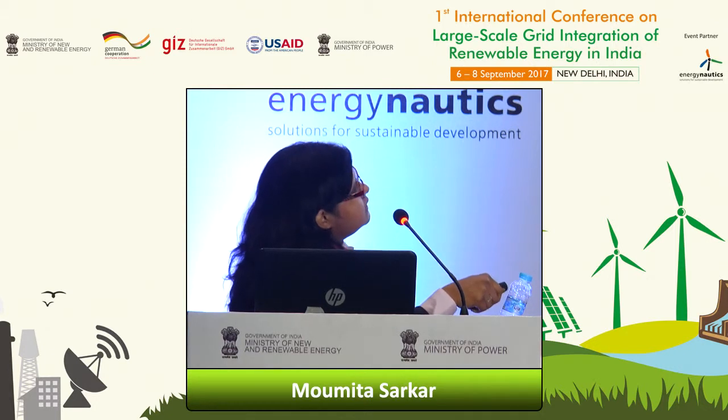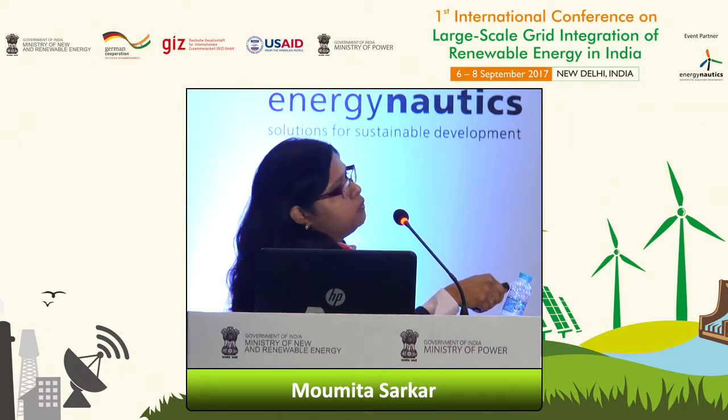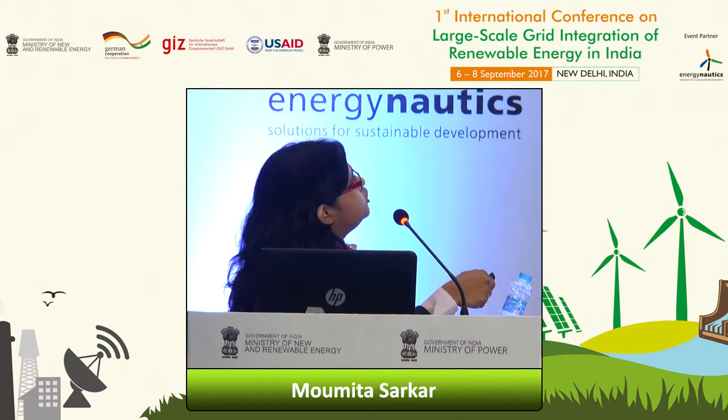With this long 150 kilometer transmission line, the short circuit ratio calculated here comes to about 1.52, which as per the IEEE definition corresponds to a very weak system. We did transient studies as well as steady state studies on this system.